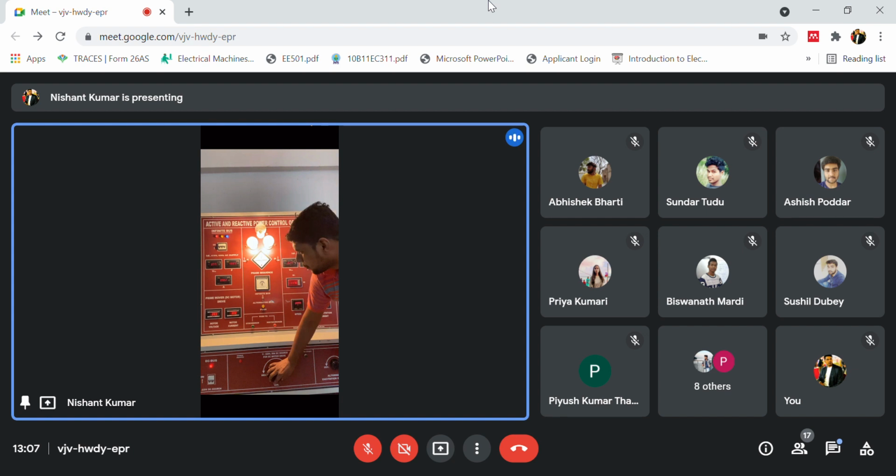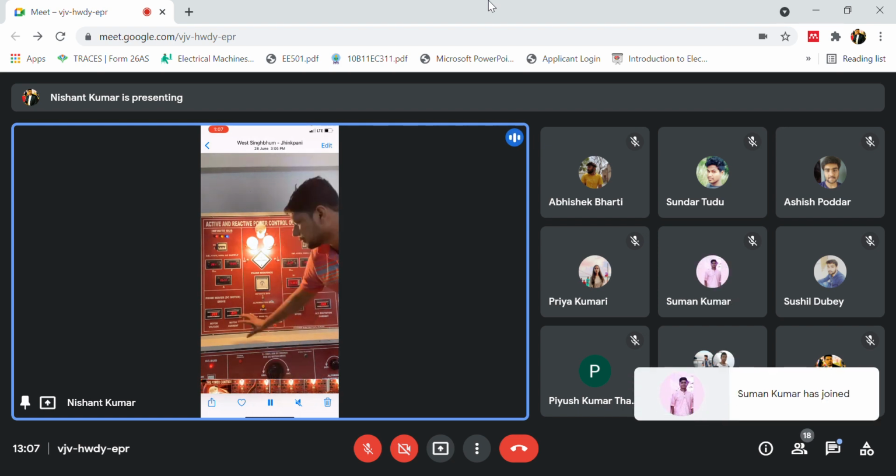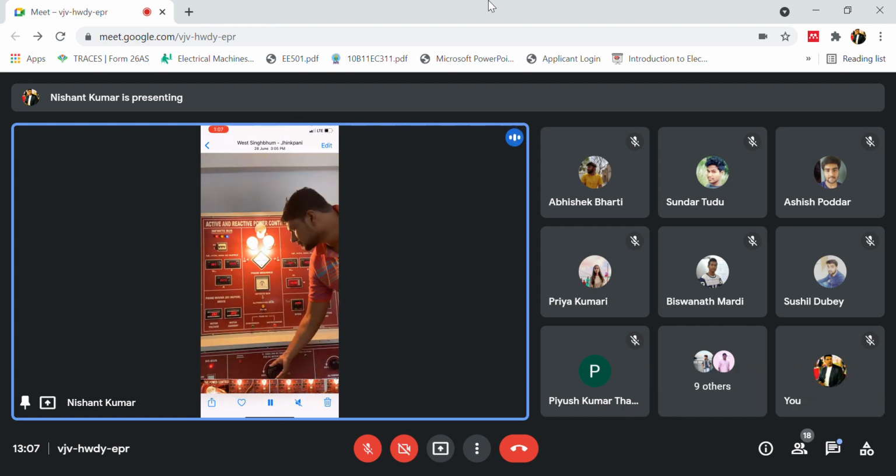Okay, the speed would not be changing, but if we require more active power to boost into any particular synchronized bus bar, this is how we control it. Okay, now we are setting it back to the normal position it was earlier.